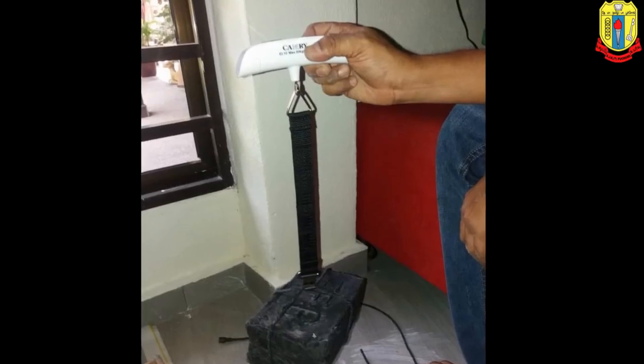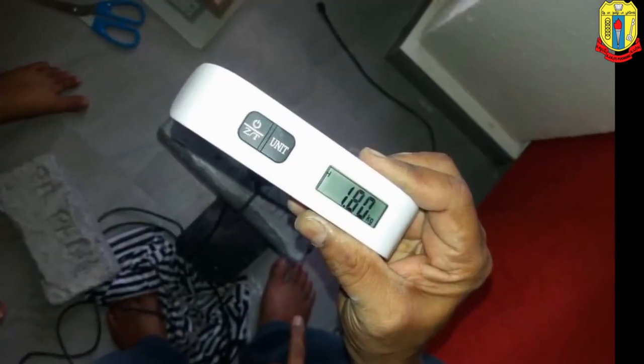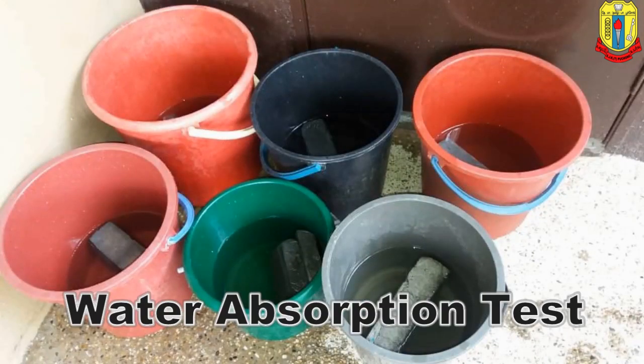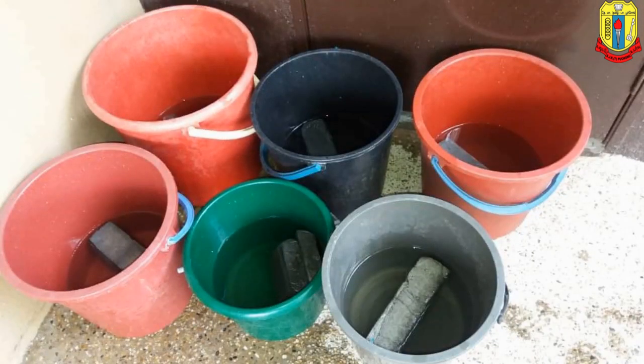Bricks testing methods. 3 tests were conducted for these bricks. The first is the water absorption test. After a curing period of 7 days, the water absorption test was conducted. In this test, the brick was weighed using a scale, then it was immersed in water at room temperature for 12 hours.